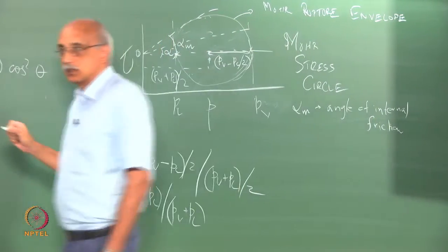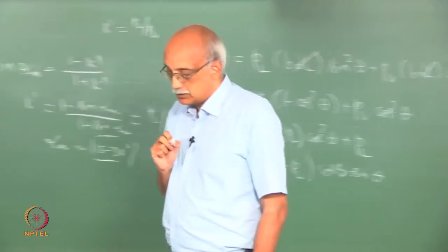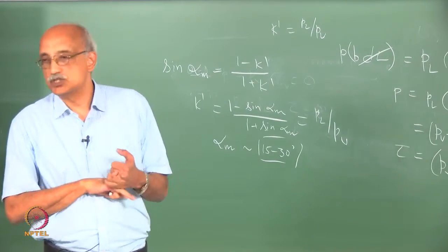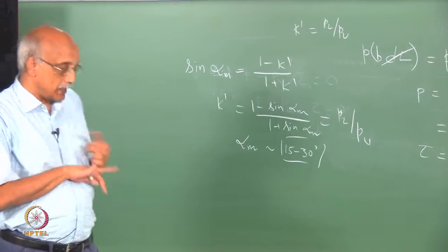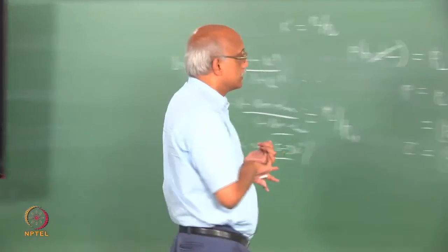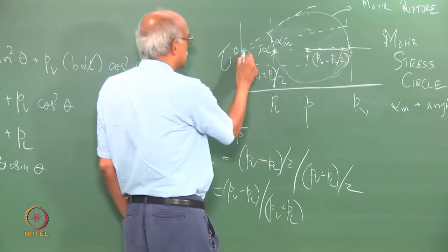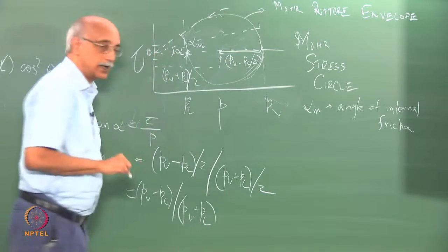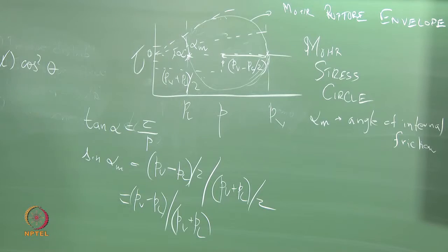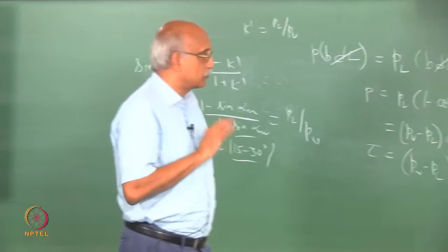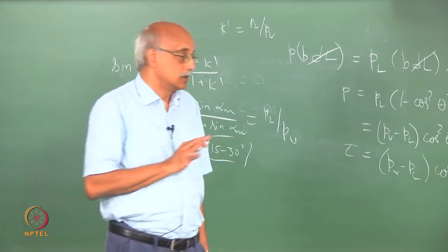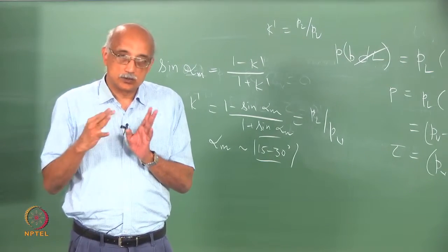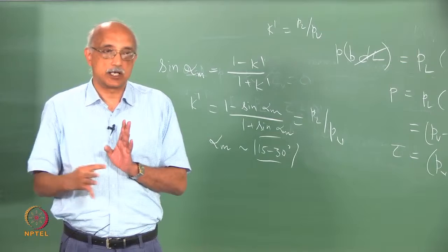This kind of behavior can be observed when you have a particulate solid that is non-cohesive and also fairly homogeneous in nature. If you have a cohesive solid, then the tangents here do not necessarily go through the origin. So, they are likely to intersect the vertical axis either above or below the 0 point. So, a cohesive homogeneous solid will have a very different behavior from a non-cohesive homogeneous solid, and also a homogeneous solid itself will have a very different behavior from a heterogeneous solid.